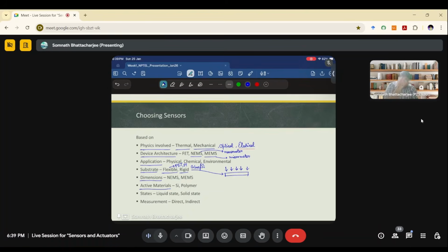So what is a biocompatible structure? Let's say if I am using a specific sensor outside of a human body, we don't need to change any kind of material. We need the stability and we need long-time usage and these kinds of things. But if we are using a sensor inside our body and we need to implant it, and we are using a silicon sensor or a germanium sensor inside our body over time, it will harm our body. It is not a biocompatible one.